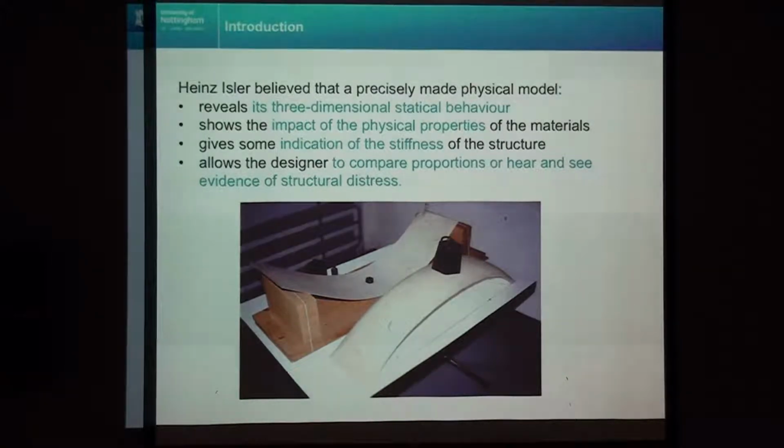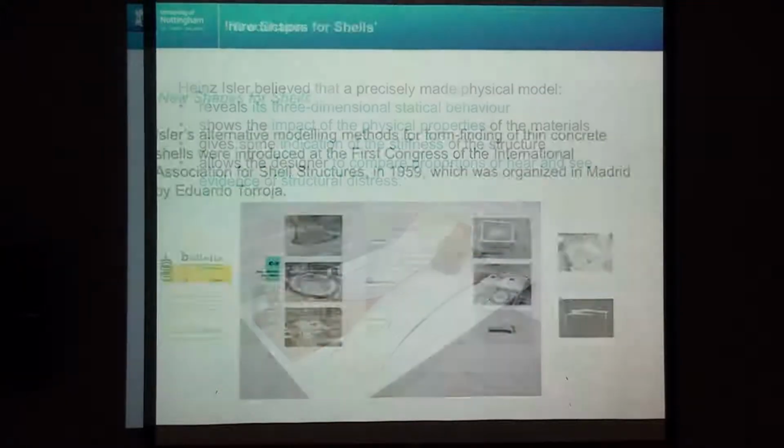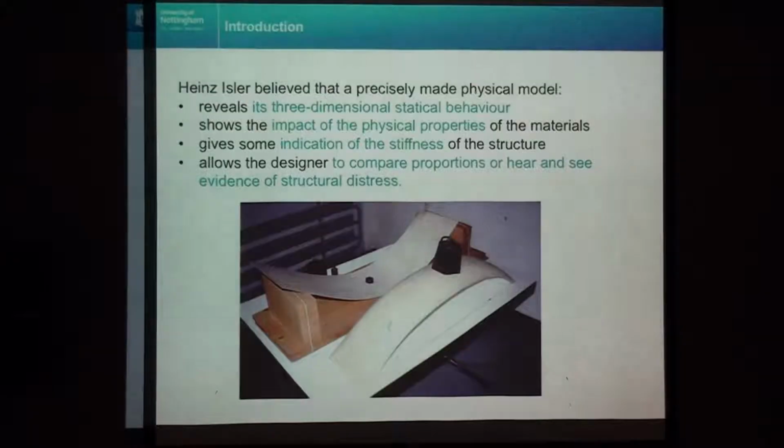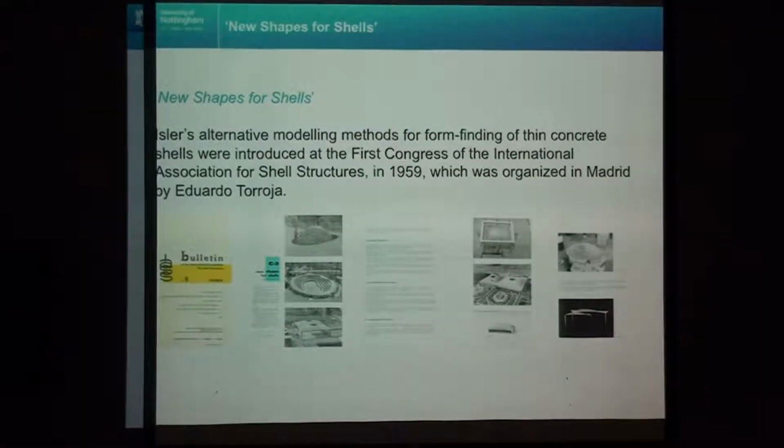As I think it was Juan showed this morning, this example he had in his office of the flat plastic sheet, which is acting as a beam over two supports. Very small load on that and you get the massive deflection. The deformed plastic sheet into a double curve structure, and you can put 30 times the load onto it, and it barely deforms.